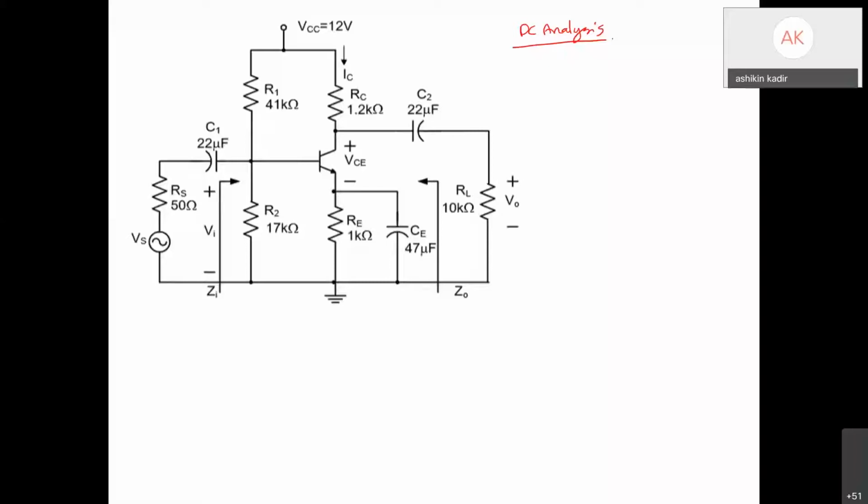So firstly, we need to determine our IC. What we can do is use Thevenin theorem. Firstly, DC analysis to find the IC. So how to do DC analysis? During this analysis, we know our capacitors are open circuit. Open. It cannot conduct current. So what's left on the circuit is, this one is open, and also open here.